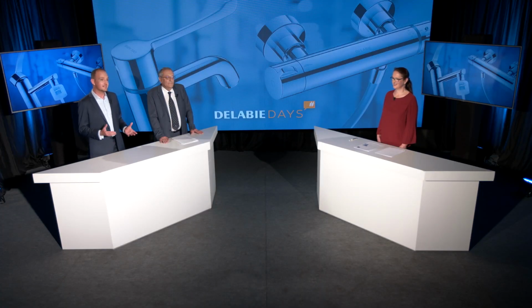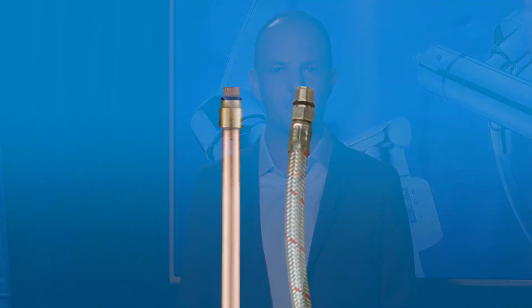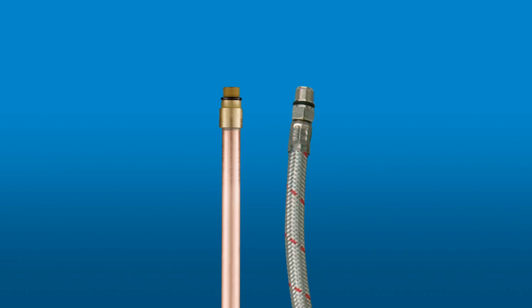What does that mean? Okay, so let's take the French medical standard of 2017 concerning tapware in medical facilities. This standard banned EPDM flexibles and aerators in healthcare facilities in France. Delabie anticipated this standard following the alert of the UK Department of Health in 2010 regarding the use of EPDM flexible hoses. And since then, Delabie offers mixers with copper tails or PEX flexibles as standard.